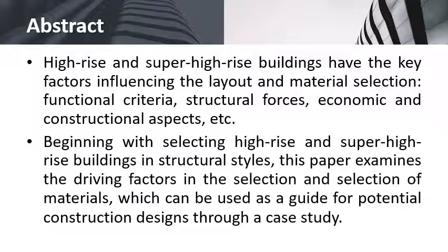Today I will start my presentation on selecting materials and loads applied on high-rise and super high-rise buildings. First of all, high-rise and super high-rise buildings have key factors influencing the layout and material selection, like functional criteria, structural forces, and economic and structural aspects.